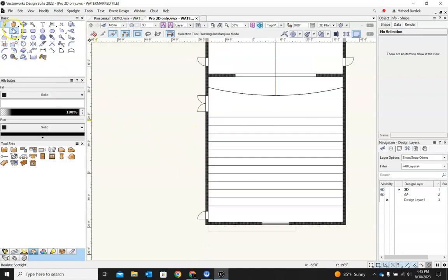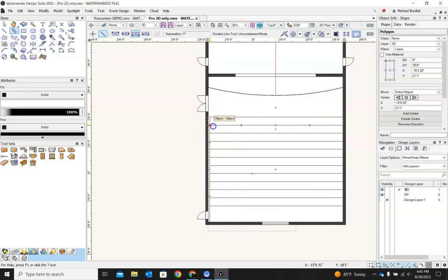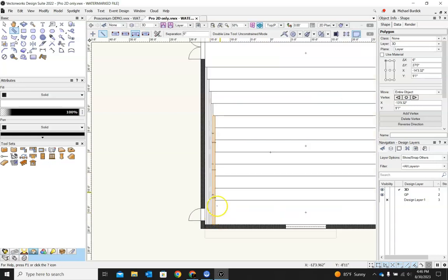But so we know all of our steps are 6 inches high, and they step up as we move from step to step. So what I'm going to do is make this 6 inches. So I'm going to build the profile along here. I'm just going to run 6 inches there. And I'm using these other ticks as guideposts.